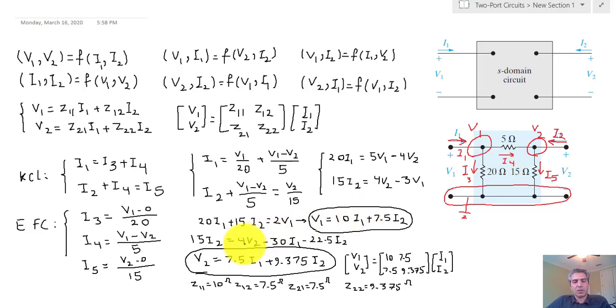All I need to do is to give them this matrix or these 4 parameters, and based on that, the user can actually replicate the functionality of that circuit using this equation that we have right here. In other words, there is now a set of equations that relates the current and voltages of the 2 ports of this circuit, and they can use it to do any calculation that they need.